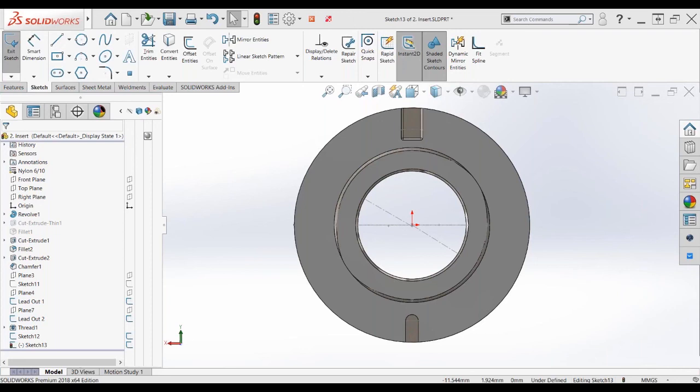Because you can insert parts into parts to get a multi-body part. So you can have part A open, and then you can insert part B into it, all in the part environment. And you can even locate it with assembly mates to then make a multi-body part, which you could then grab those two bodies and combine into a single part. But I'm not sure if that was the intent of your question or not. But I'll give you a couple minutes if you want to rewrite that question so I can better understand it and get you the answer you desire.